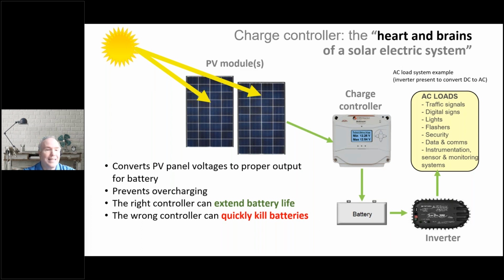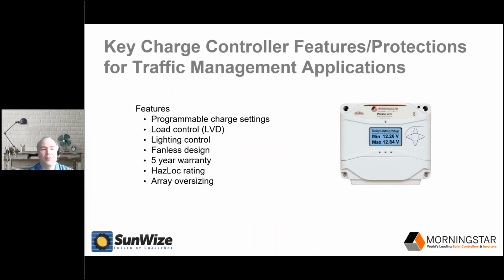That said, I'm going to stay on the charge controller topic and go to the next slide to cover some of the features and protections associated with solar charge controllers. Depending on your application and the types of batteries that you're using, you may want to use a controller that has programmable charge settings. For example, the ProStar MPPT controller on this slide has interactive scroll buttons that allow you to change absorption and float voltages and times according to battery manufacturer specifications.